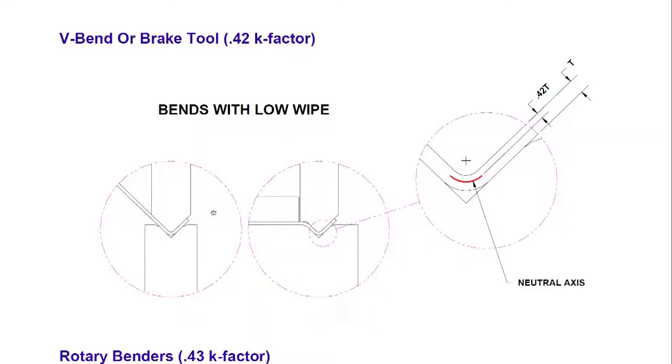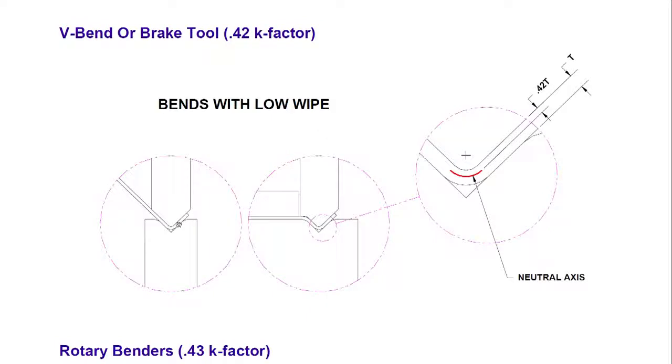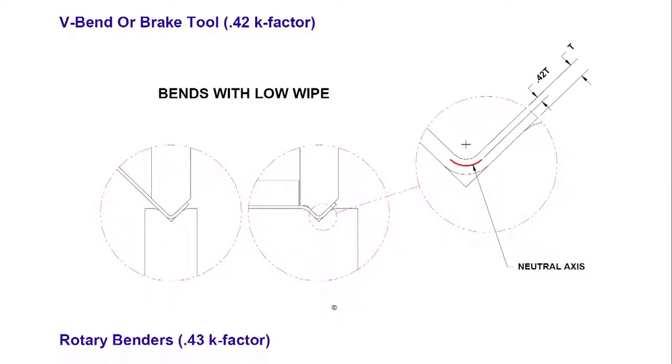Towards the end I showed you the V brake. So, we have a punch on top, then we have a die at the bottom, and then you see how the bend takes place here. Here also 3 types are there. One is if you have a gap, we call it air bending. If both sides are pushed and then we hit both of them together, it is called coining. And then we have normal bending which has other operations.